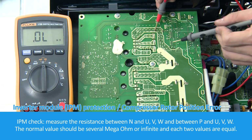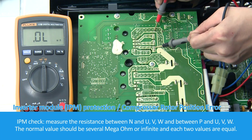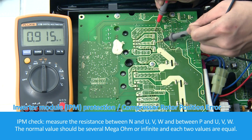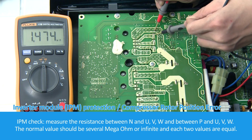IPM check. Measure the resistance between N and UVW and between P and UVW. The normal value should be several mega ohms, should be infinite, and each two values are equal.